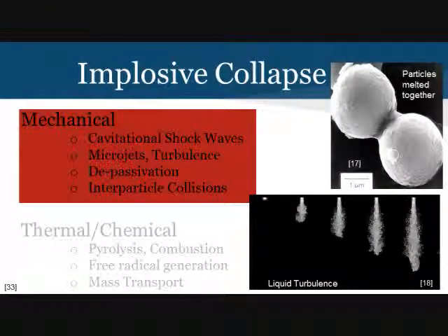Implosive collapse forces all of the energy in the form of shock waves to be expelled at one point in the microbubble. When the gases inside the microbubble rapidly condense, these particles collide with one another, forming cavitational shock waves. These waves create microjets and liquid turbulence, which you can see in the picture in the bottom right, and these heavily reform particle surfaces or help to mix solutions.